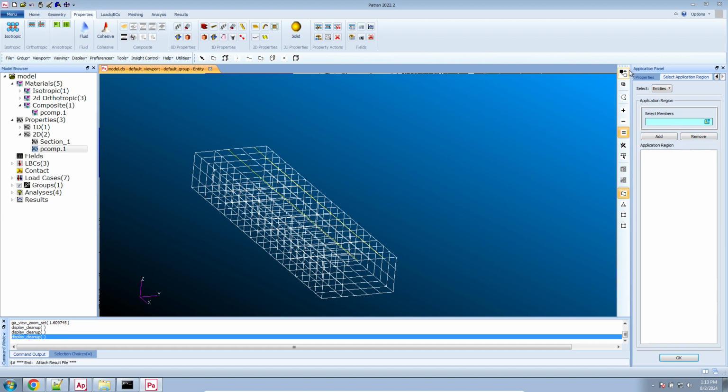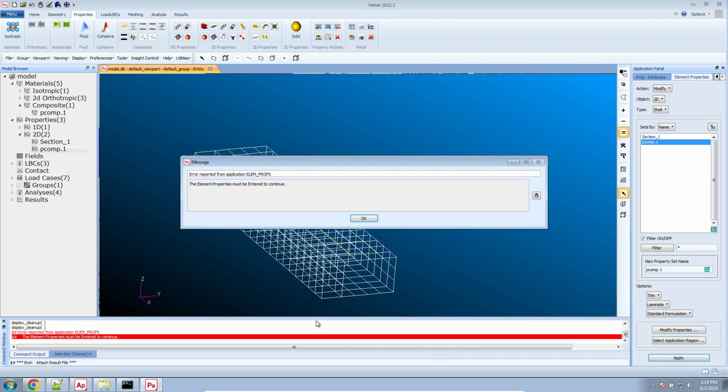And remember, when you select objects, you can select geometric options. So here if I try to select a geometric option, there are none. There are no geometric surfaces to select. So what I'm going to do is click on this button, shell element. Now if I select objects, I can select all the 2D elements. So let's go ahead and click add, click OK, and click apply.